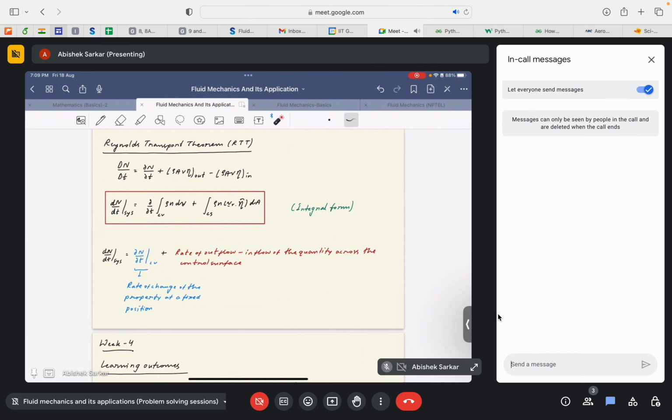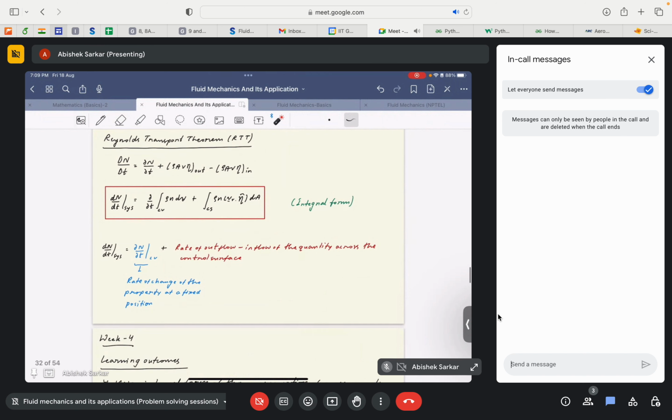and its simplified forms, eventually when we apply this theorem to energy conservation and simplify the energy conservation equation for certain assumptions, we finally obtain Bernoulli's equation. Since it has a far-fetched implication in the field of fluid mechanics, I felt that it would be good to start with it. In simple words, the Reynolds transport theorem acts as a transformation from the control system to the control volume approach. So I guess I should write it.